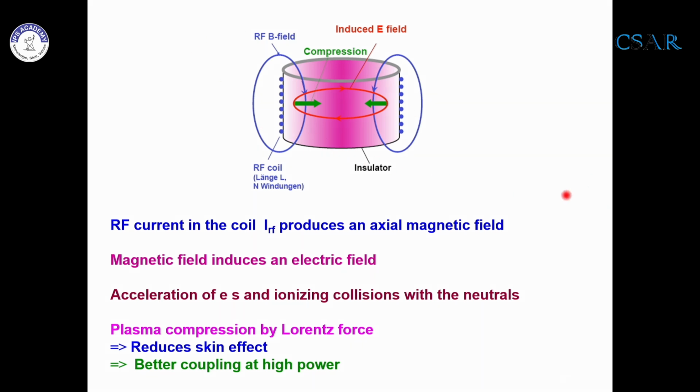And in this system now, if there are stray electrons that are generated by radioactivity, cosmic activity, or whatever it is, these electrons will be subjected to this electric field. They will gain acceleration along the direction of the electric field. They become energetic, and because they gain energy, they create further ionization. And this circumferential current will now be flowing in this loop.